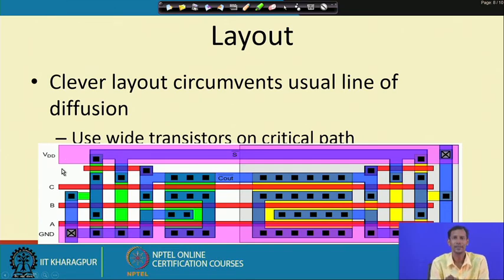So, basically this is part of VLSI design. The pink color lines are metal layer lines carrying VDD and ground. VDD is connected to the supply voltage, and ground is connected to 0 voltage. Then I have A, B, C as the inputs that are connected over here. And these black dots are nothing but the connections between the layers, which are the vias.